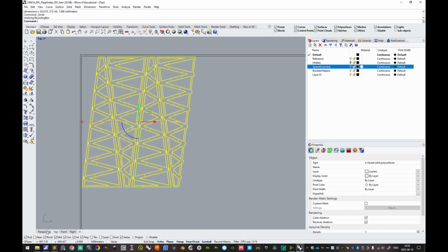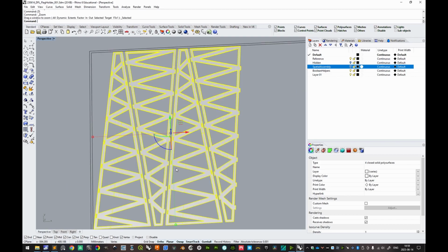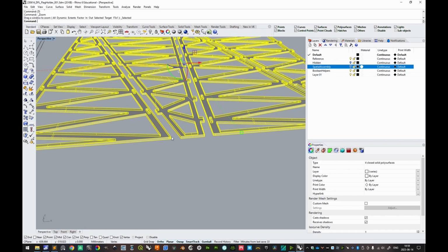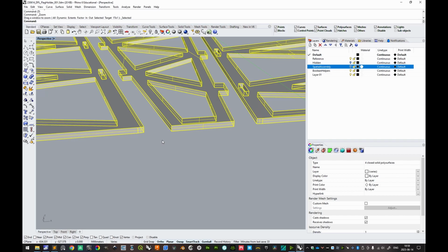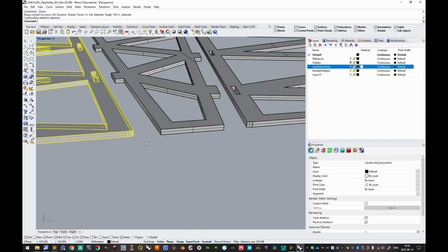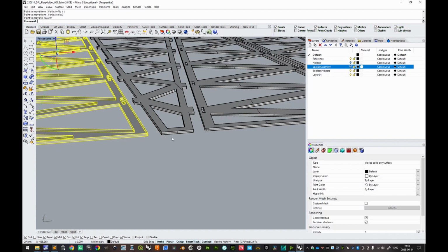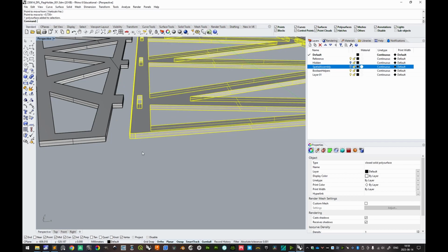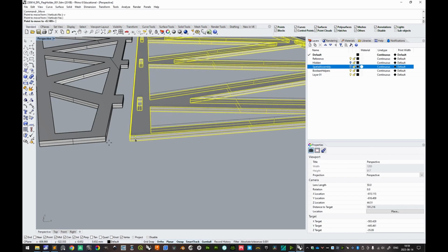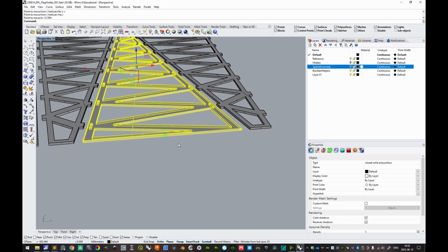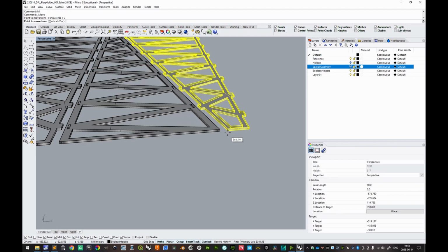Now we need to go to the perspective viewports and zoom to selected to make sure that these are correctly aligned in the Z axis. So we'll select the first one, move vertically, first point, second point. Yeah, we saw there was a deviation there. So now these 2 are correct, and then we'll use this one to correct this one as well, and the last one.